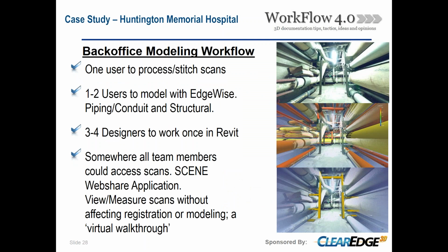So we've been trying to train multiple people on using the scanners. The particular scanner we're using is pretty user-friendly. So it's quick for me to say, here's how you scan it. You basically can just set it up and it kind of does its thing, but you have to have a keen idea of what the laser scanner is trying to do. It needs to have line of sight; it's not going to be able to look around walls. So we usually try to take as many scans as possible, within the time limit, just so we make sure we cover all our bases and there's nothing that we missed.